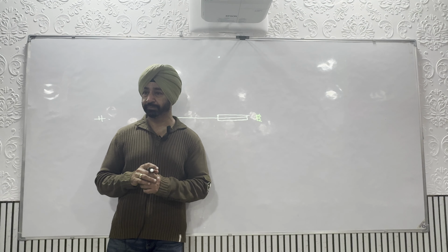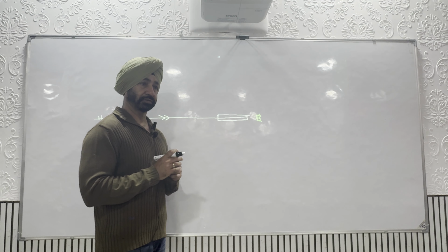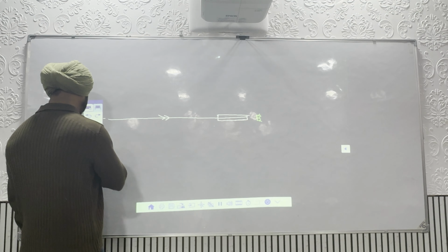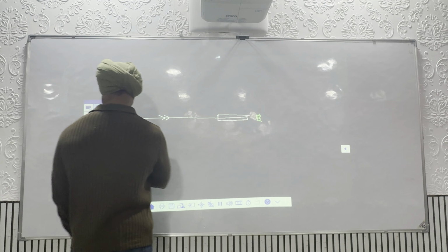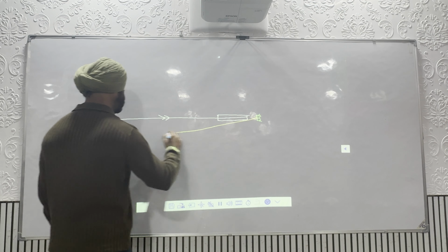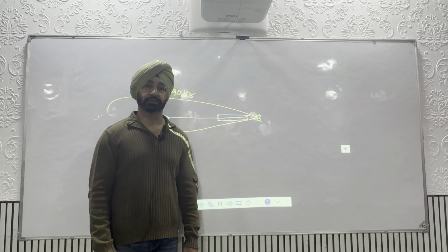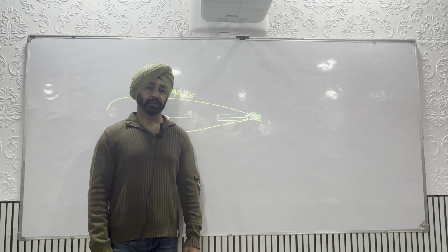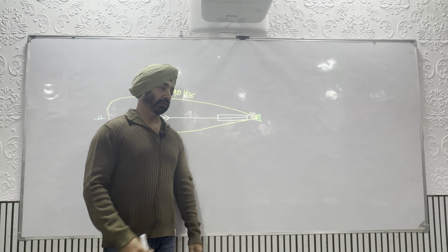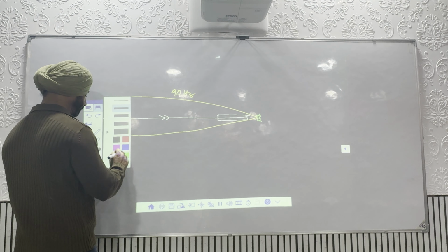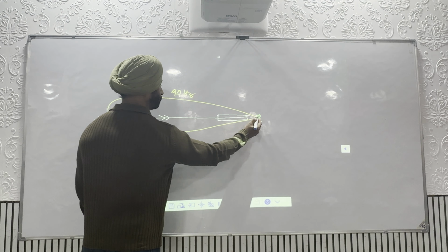Now, what the information is transmitted on, that is, there are two different directional lobes in the approach direction. On the left side of the approach, it transmits a directional lobe of frequency 90 hertz, and the same antennas transmit another lobe of 150 hertz, which is on the right side of your approach direction.